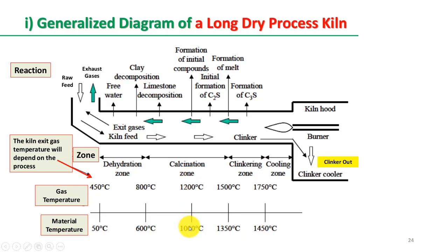In calcination, basically your material becomes so reactive that it can react with the other products, fuse into other materials and sinter below the melting points, so that it can have a clinker formation at around 1450 degrees Celsius. After the calcination, you can see that there is a clinkering zone. When the calcination happens, the material becomes so reactive that it can react with the other constituents like silica, alumina, and iron, and calcium can react among each other to form a clinker.